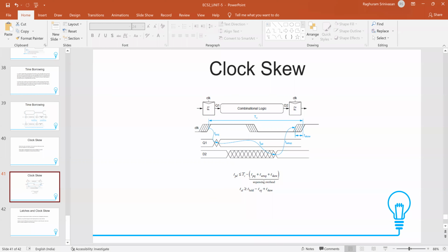In most cases, the clock period will stay the same, okay, but the arrival of the edge can be pushed forward or backward. This is because of the delays in the wires. Some neighboring wires may be switching, and the switching will be different. So in different parts of the clock network, the clock skew will be slightly different. That's what's shown in the diagram also. But the maximum number is given as T skew. What is the maximum amount by which the clock can change? And in that particular case also, your design has to work.